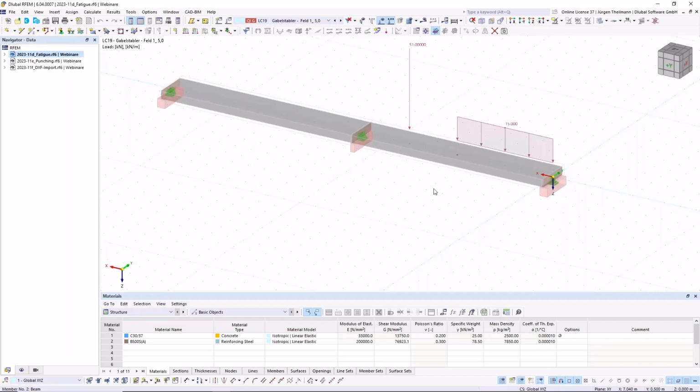And this leads me to the next part of this question. Where do I need the fatigue design? It's mainly developed for bridge design, but as I said, other traffic routes, and maybe you have some rainwater basins with traffic around. So you can generally say the fatigue design is for structures where you have a lot of load alternations with load cycles of 1 million or more. Then maybe you will need to perform this fatigue design check.